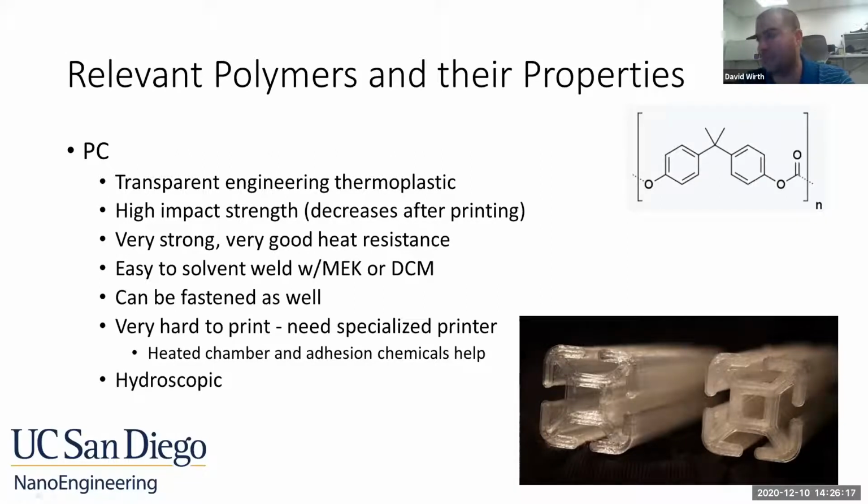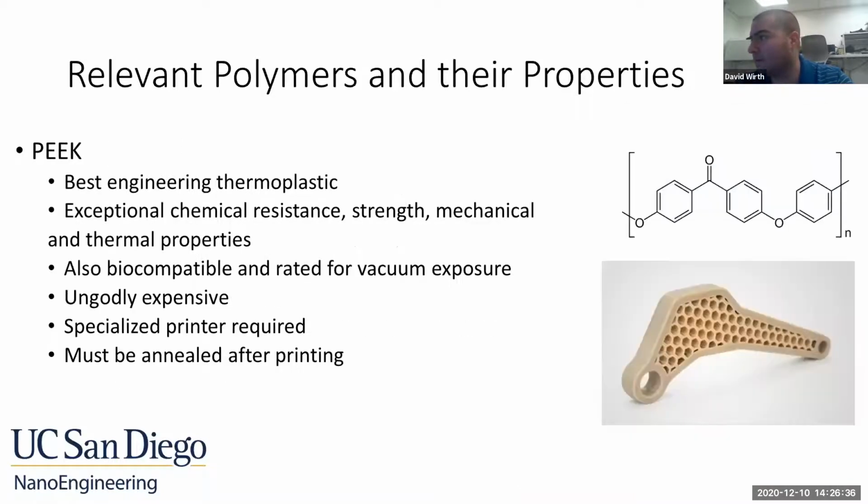It's easy to fasten together, easy to solvent weld, good heat resistance, obviously. But you have a lot of bed adhesion issues, similar to ABS. And generally, you need a heated chamber to prevent warping. It's also pretty hygroscopic as well.